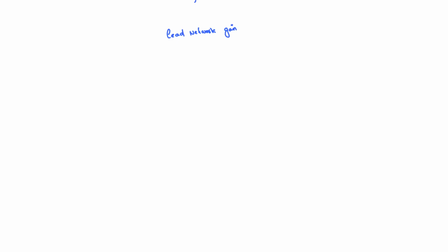So to do that, let us have one example for the lead network. So what is the lead network? I am just trying to talk about only the voltage gain response here. In this lead network, I am giving a particular AC signal. That AC signal I am passing to a capacitor C, and I am taking the output across the R. When I show this lead network, it means the output voltage is leading the input voltage. Here my input voltage is a sinusoidal signal.